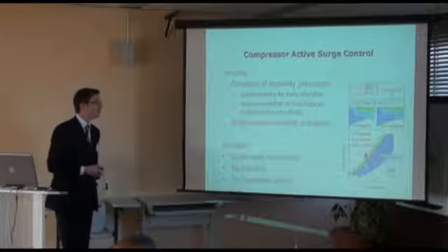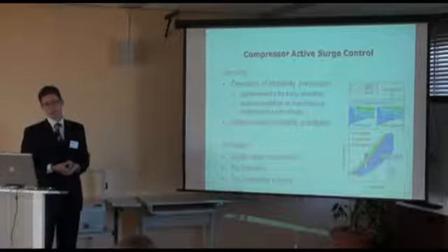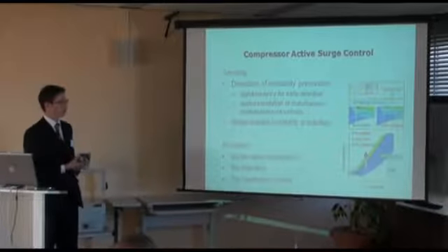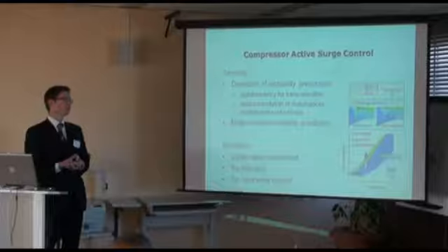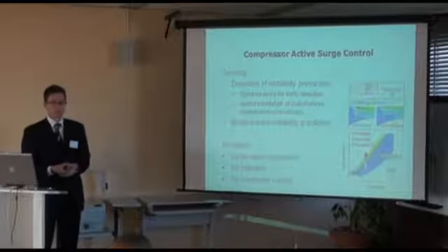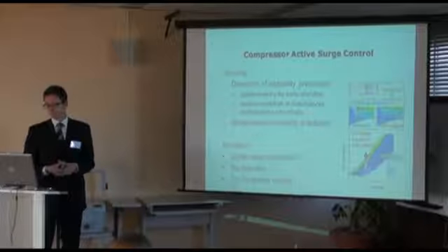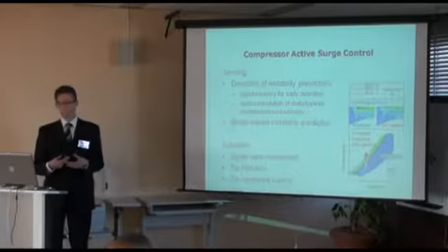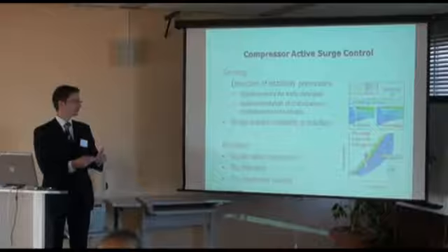You also can have model-based instability predictions. So you would have an onboard model then, which periodically calculates your current and future surge margin and then predicts the event which is coming up.